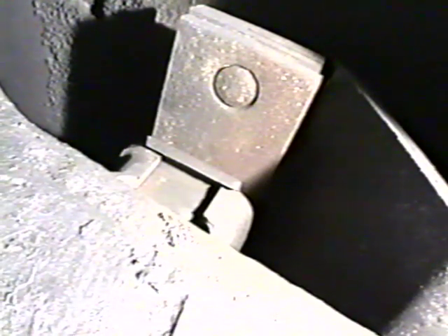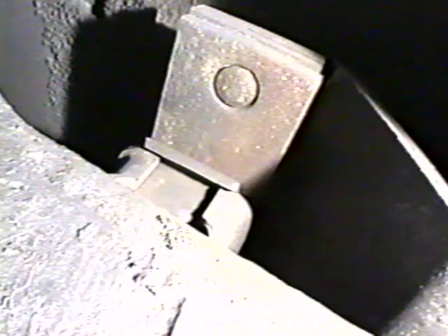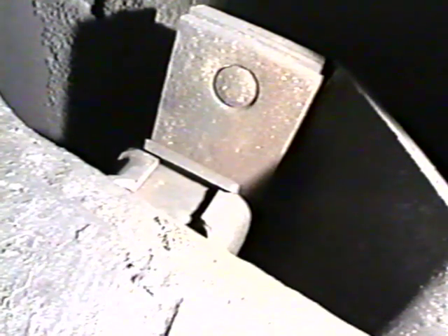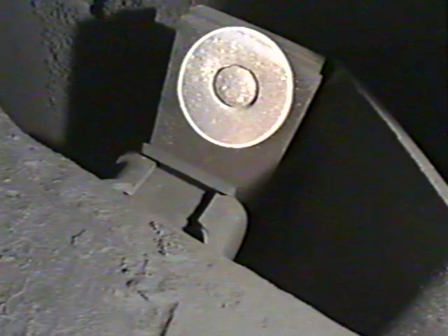This can cause excessive truck turning resistance because the side bearing must slide on its wear plate for the truck to rotate properly. Another side bearing problem that can increase the truck turning resistance is protruding wear plate fasteners that interfere with the side bearing.